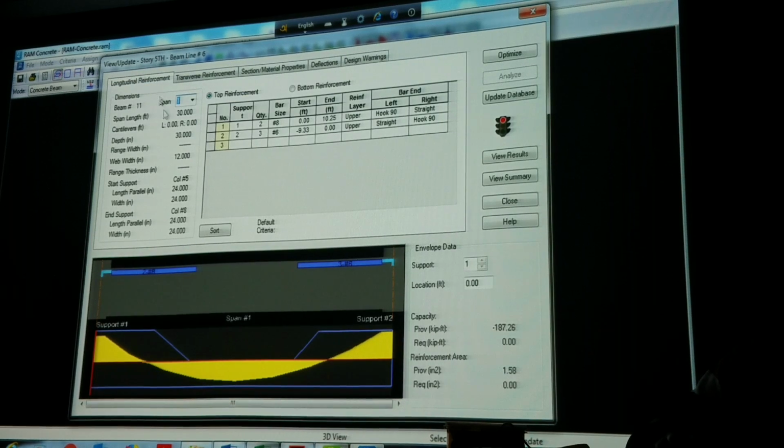The other thing is, if you look into that for normal bending, it shows me all the reinforcement. That means we chose a 12 by 24 inch beam. For normal bending, on the top side, 2 number 8s is fine. We are talking about top reinforcement. First interior support 1 is 2 number 8, support 2, 3 number 6, and it goes on if you want to get into more.